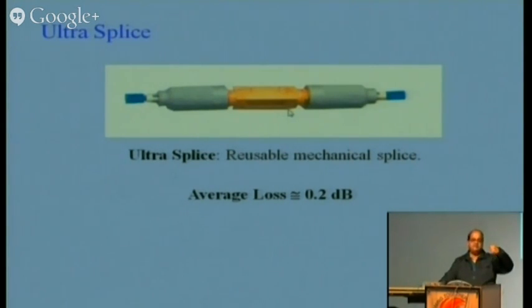If it is a 125 micron cladding, the diameter may be 130 micron, so that there is no axial offset. There may be a gap because longitudinal loss is not very crucial, but axial is very crucial. So we have these types of splices.